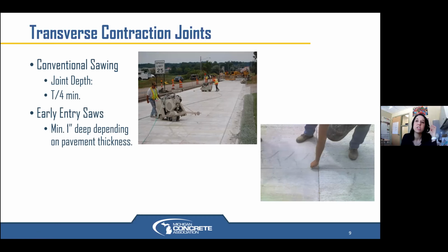Okay. And then we have: saw cut timing may be different to capture unless there's a maturity meter installed or the contractor is monitoring the concrete's internal temperature. Can we share our thoughts on this? Concrete isn't perfect. Yes, those maturity meters are awesome and they're a great tool, but concrete is not super confusing. If you stick within that window and look at your temperatures, I think we can do a pretty good job estimating when these saw cut windows are.